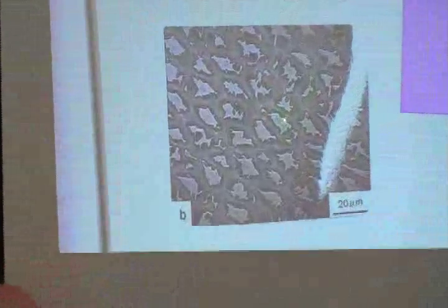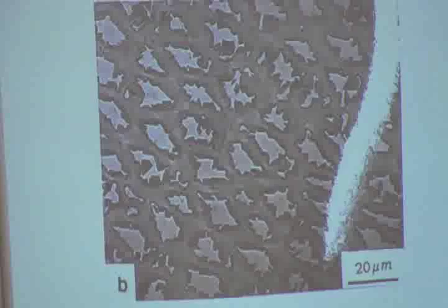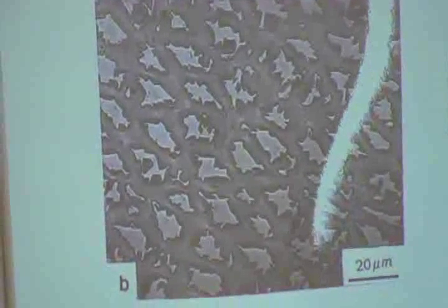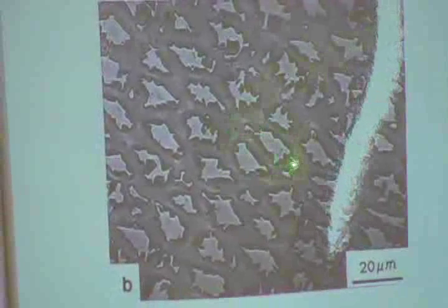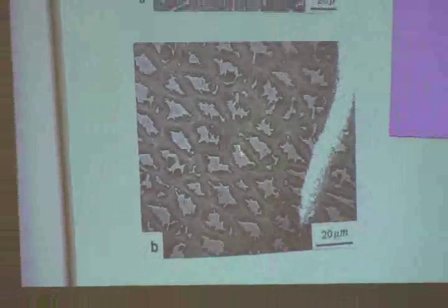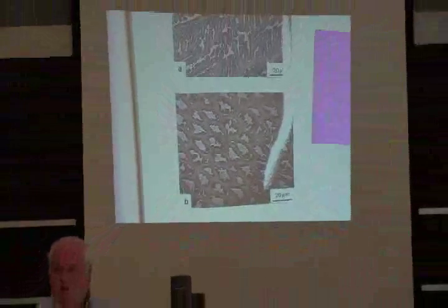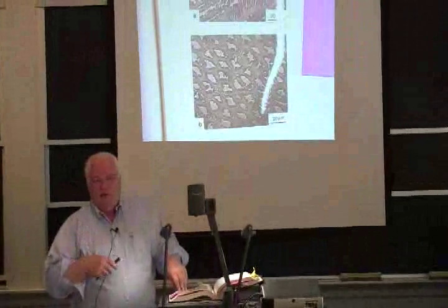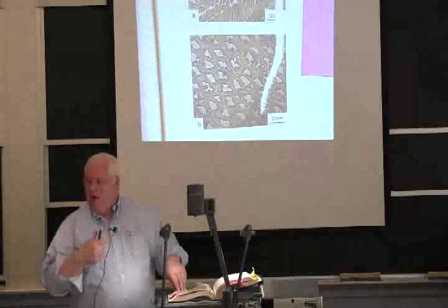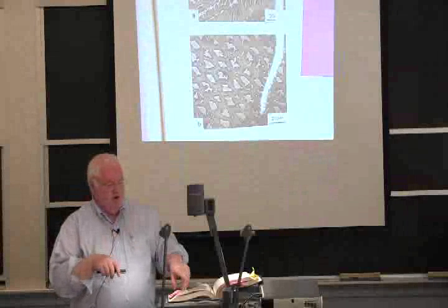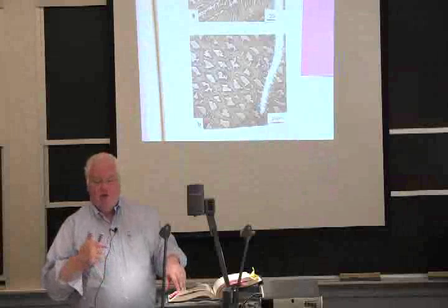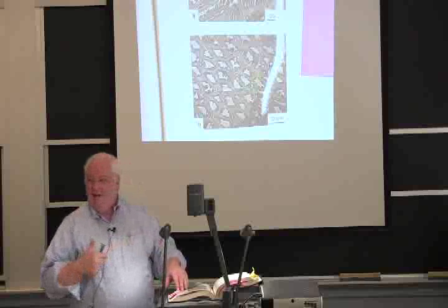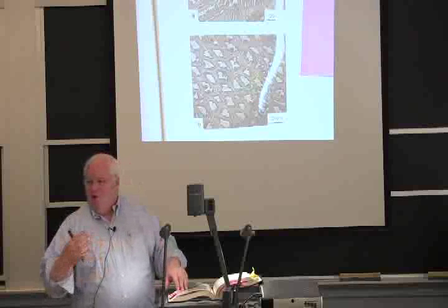The core that's fairly white is the first FCC non-magnetic stainless steel to form, and it was sort of round in cells, but as it transformed, cooling down, it rejected some of the chrome and nickel, and with this particular etchant it would etch a different color. Originally this is in black and white now, but originally it's a color etchant. You see all kinds of rainbows of colors, but you can see in this type of picture the coring.